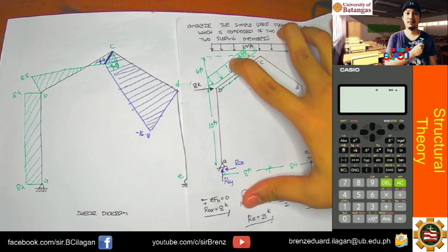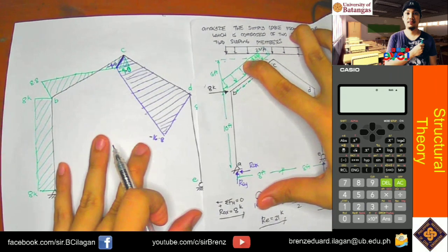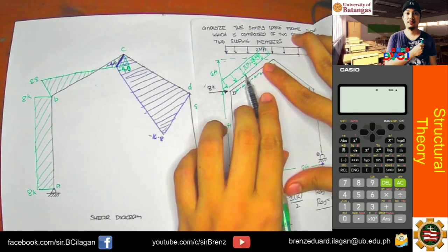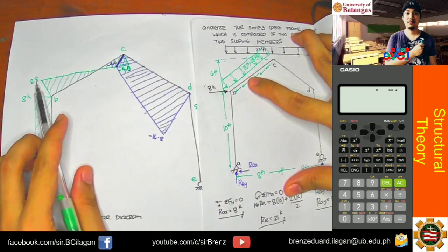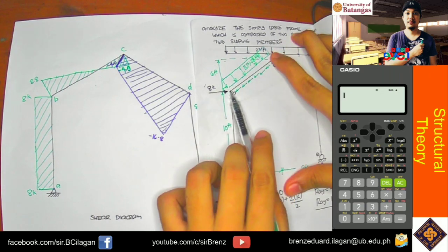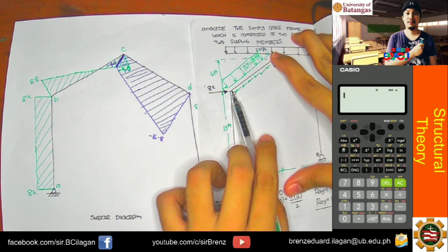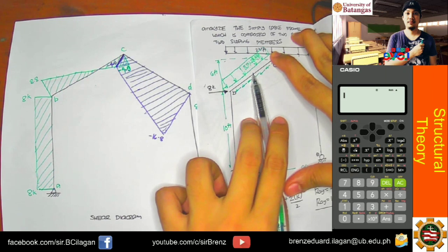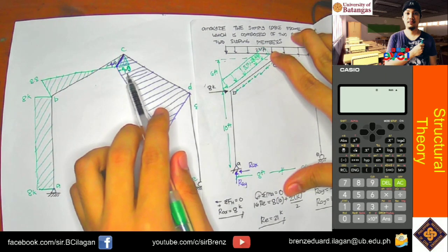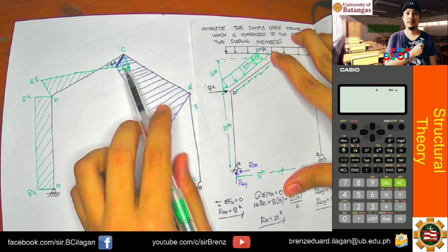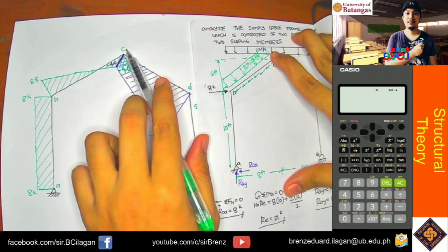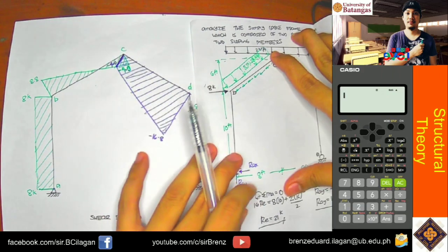So, again, coming from 8.8, di ba meron kang uniform load which is acting in this direction? Pag ganun. So, ibig sabihin, mababawasan yung 8.8 ng 1.28 times yung span na 10, or that will be 12.8. Okay? So, 8.8 minus 12.8, that will be equals to negative 4. Okay? And then, kapag pagdating dito, meron ka ditong shearing force which is going upward na 4. Kaya magsisiro ka ulit. Ano?